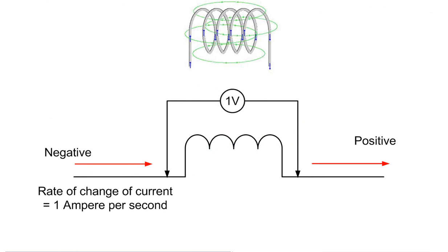Inductance is all about current. Capacitance is all about voltage. Just to remind you, capacitance is the opposition to changes in voltage. A capacitance is able to oppose changes of voltage because as the capacitor charges to the supply voltage, it pushes back against the supply voltage, inhibiting further charge of the capacitor until eventually the capacitor is fully charged and it has the same voltage as the supply and pushes back as hard as the supply is pushing forward and will not charge anymore.